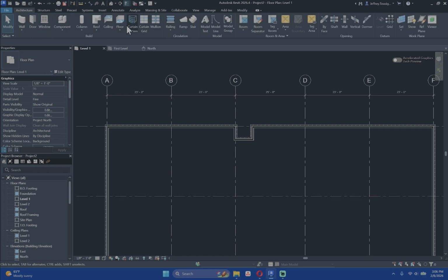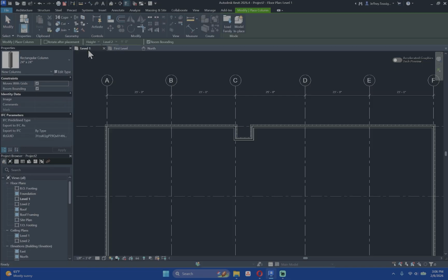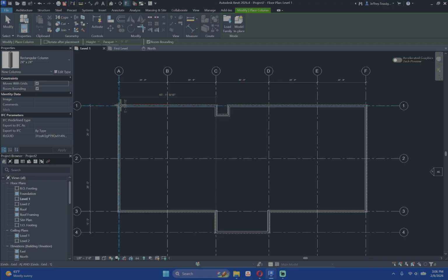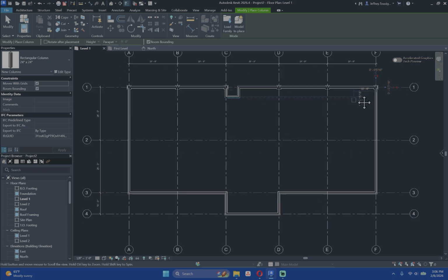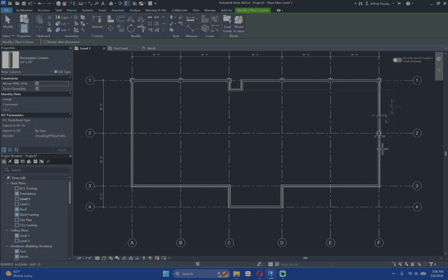I'm going to go to the Column tool, and I'm going to ensure that I'm selecting Architectural Column. I'm going to tell this column that it needs to go from level 1, which it currently is doing right now, all the way up to the parapet level. And then I'm going to select the intersection of all of the different grids where these columns would exist, which are basically going to be everywhere except for the 4 locations on grid 4 that are outside of the building.